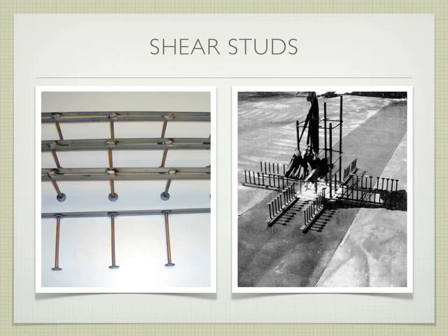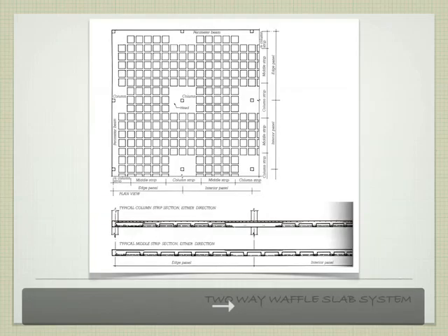Yeah. Say it again. Exactly. So they'll be completely covered by the slab. In this particular example, those are sticking up 6 inches. The slab's probably going to be 8 to 10 inches thick, so they're going to be completely covered. But that's what's going to allow us to transfer some of that lateral load down into the column.